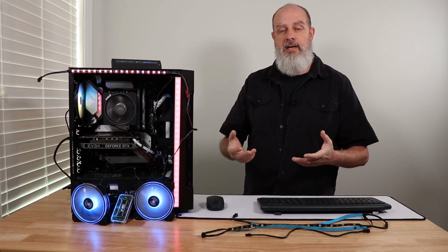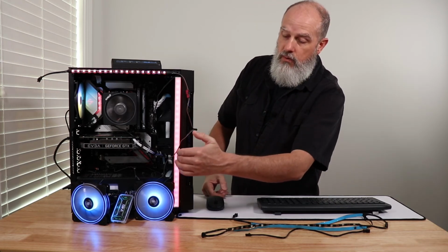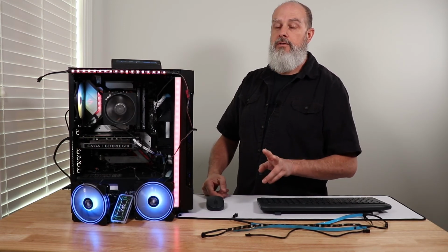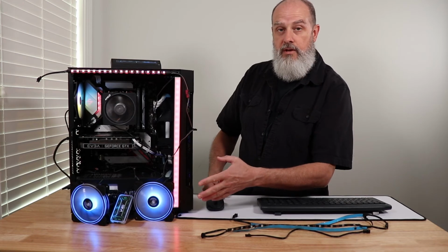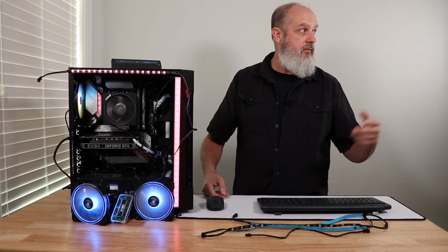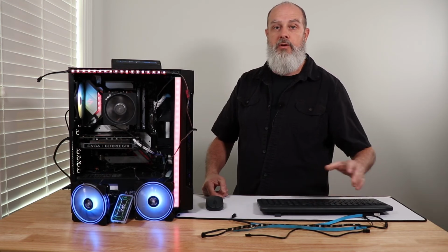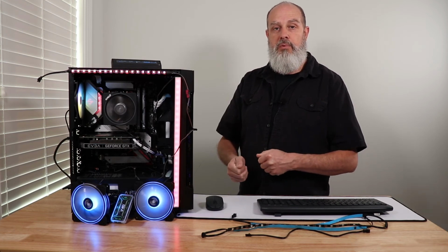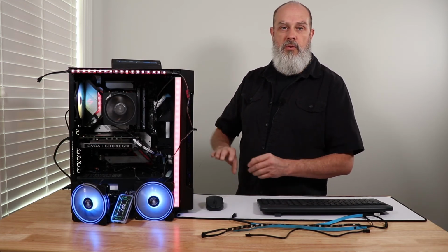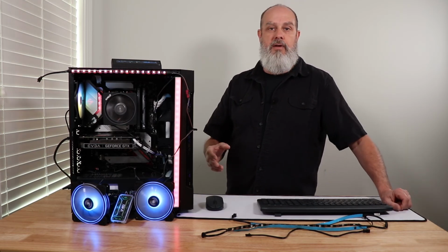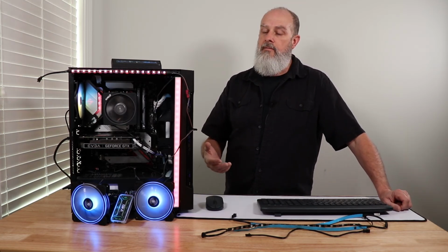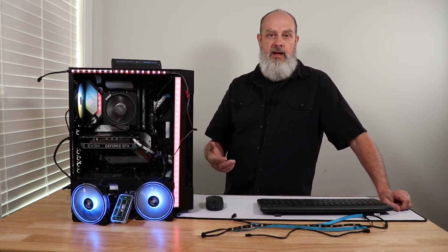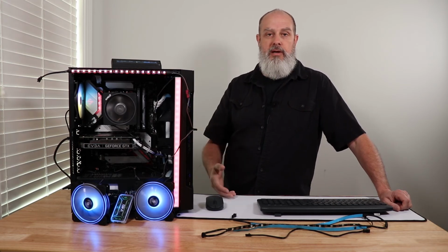Now, a couple of solutions I've seen to this online: this motherboard in particular, this ASRock one, has 4 RGB headers, 2 5-volt, 2 12-volt. It would be important to know that you can use those all at the same time using the software. You can do all of them at the same time or do them individually. But you could take these 2 5-volt headers, plug in 2 5-volt splitters, and then at least you could get dual colors and dual effects on individual fans, but you would still just get those 2 channels. Again, Corsair defeats this in a more fanciful way, with the software and the hardware, because the component is actually daisy chained.